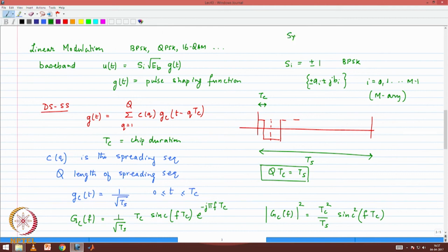Never have a confusion between symbols and chips. Whenever we refer to chips, that means we are referring to the signal which has already been spread. Symbols are transmitted in the spread spectrum system, but could also be before or after despreading, so we have to interpret them carefully. In general, the convention is that symbols means the narrowband system.